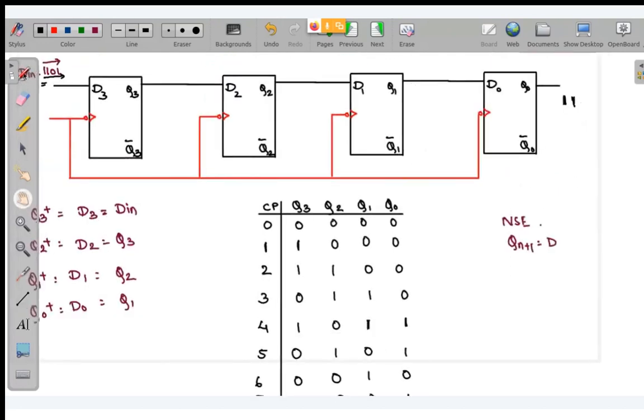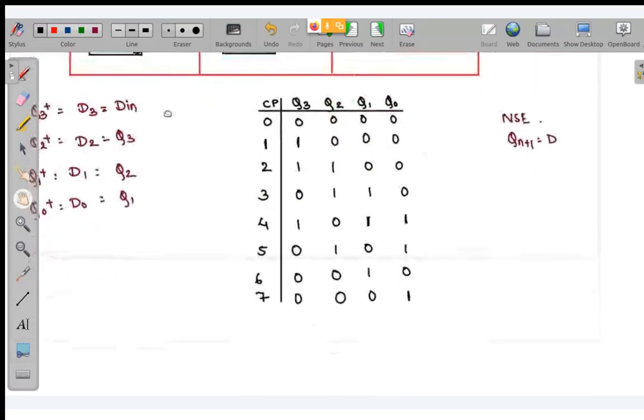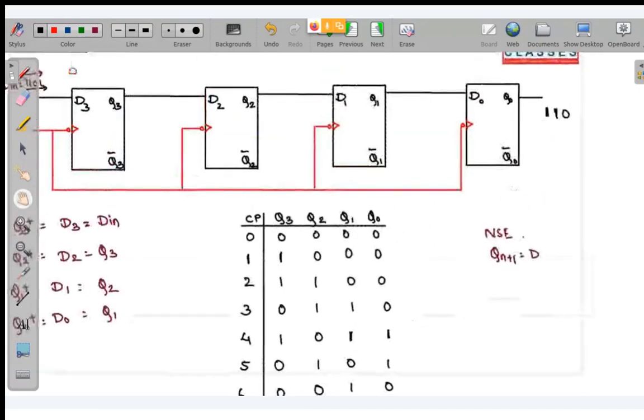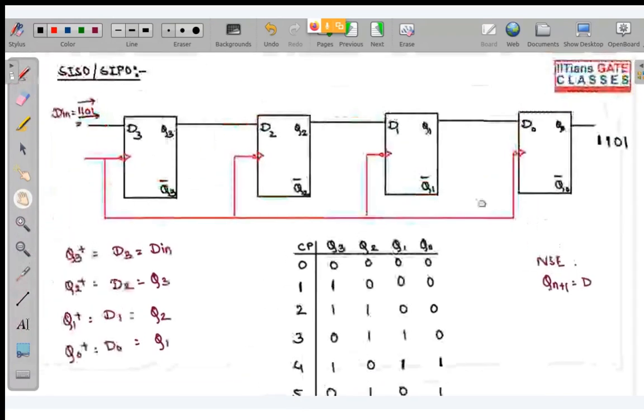So this is now over here 0. And in the last clock pulse, that is your 8th clock pulse, this will become completely 0 once again, and this one will also be popped out of the register. So this will become 0. So you can see basically the data bit that was entering, in the same order we are getting the output also. Now I told you in SISO, the only thing accessible to us is your input terminal and your output.